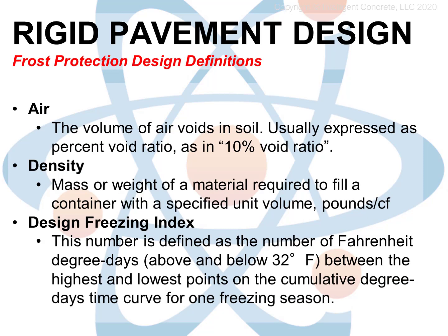Now we're going to talk briefly about the effects of freezing on pavement design. In soil, we have, obviously, soil particles. We also have air, water, debris, and organic materials. Hopefully, our subgrade below our new pavement doesn't contain trash or organic materials, as they will slowly decay and leave voids, and voids lead to settlement and damage. But there will be air and water. The air we're going to try to drive out by compaction, but we're not going to be able to get rid of the water quite so easily.